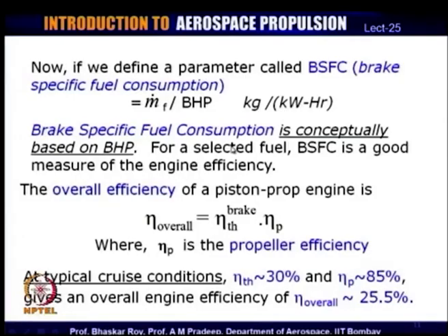Now, brake specific fuel consumption is conceptually based on the BHP. Conceptually you can again have an indicated specific fuel consumption, where instead of BHP you can use IHP, but as I mentioned, the more useful one is the brake specific fuel consumption. So, when we say BSFC, we are talking about the utility of the fuel in terms of the brake horsepower, the final horsepower that is available from the engine.